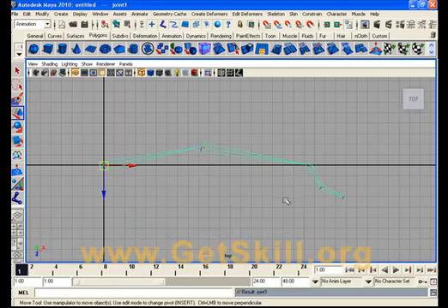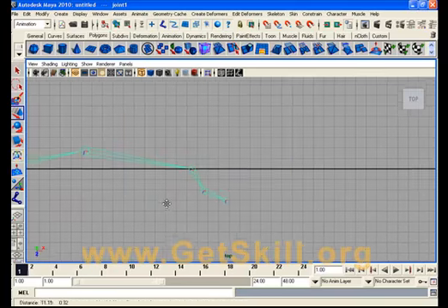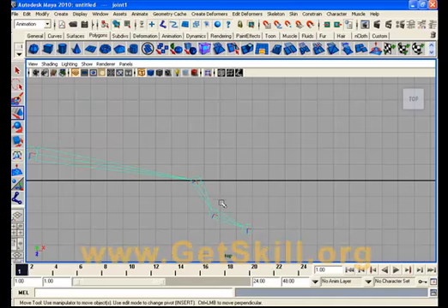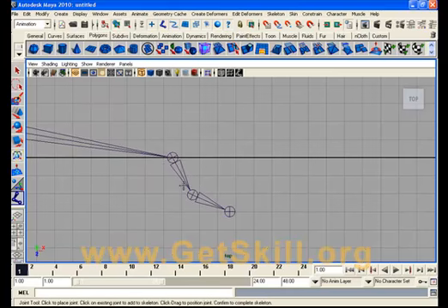As you know, you are drawing the joints for an arm, and this is the time to draw the joints for the fingers and the palm. Simply we need to add some joints for the index finger. Click the wrist joint, then draw the palm joint and 3 joints for the index finger.